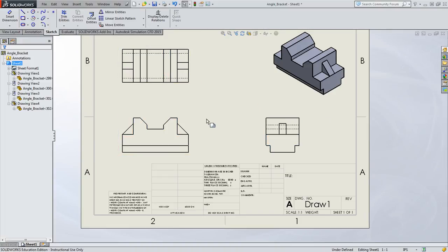It's up to you to decide later, when you're thinking for yourself, which views work best for which dimensions: heights, widths, or depths. But it's best to group them together if you can. It's not always possible. However, it's a drafting convention. It's not a standard that you have to follow blindly. It is something that you try to observe.